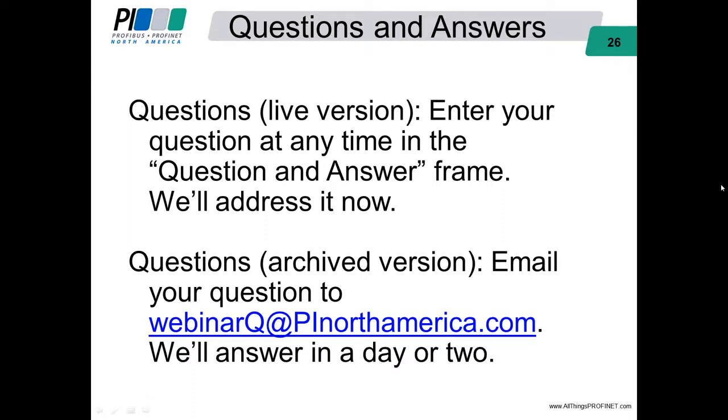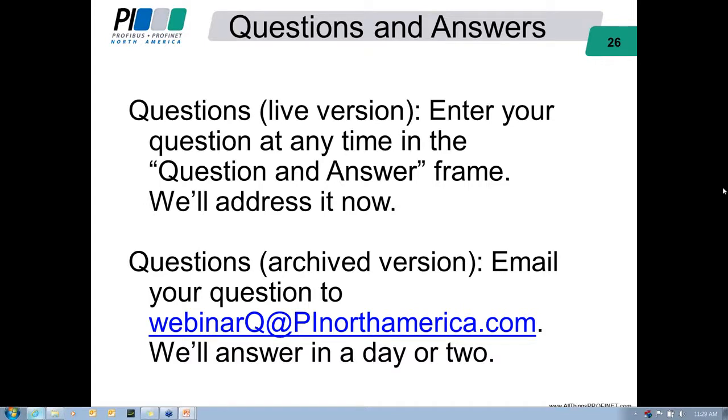I have a question that I think I'm going to refer over to Hunter. Someone has asked, how do you configure your system to use PROFIenergy? Hunter? Okay. The PROFIenergy profile is basically, again, an application profile that runs on top of PROFINET communications. So what the PLC manufacturer will provide you in your I/O controller is some programming blocks. So it's usually some PLC programming blocks you'll use in your PLC application, and that'll give you the ability to do the start pause and stop pause commands and the PROFIenergy commands that are available to set up those timings, like Carl was showing in the example, where you can specify the amount of time you want to start the pause and to have the energy savings in place, and then you would fire the command when you want to start the process again. And so those are, again, provided by the manufacturer of the PROFIenergy device.